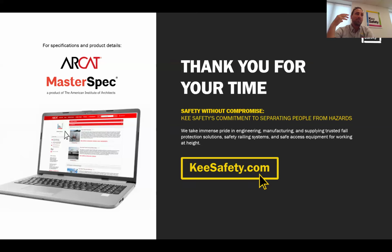Though that is like every industry in the US, there's less and less and less experts available. The best solution is to integrate collective fall protection. Collective fall protection just requires an annual visual inspection by any worker, because all you're looking for is that it's still fit for use, that it hasn't been messed with, moved around, and that there's no work being done outside of that.